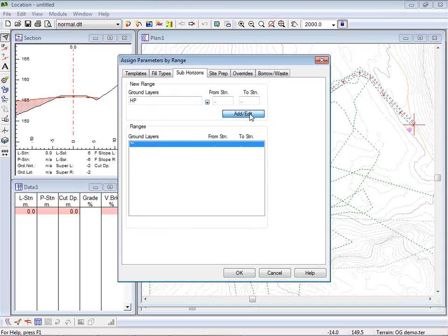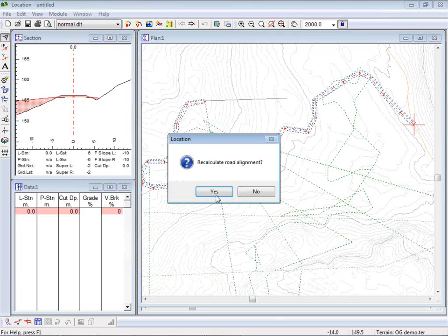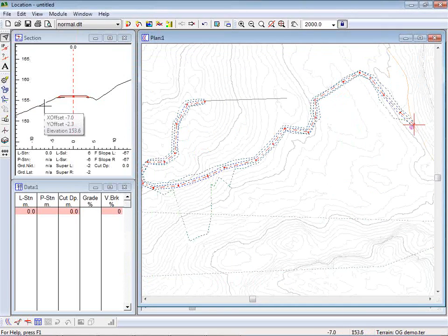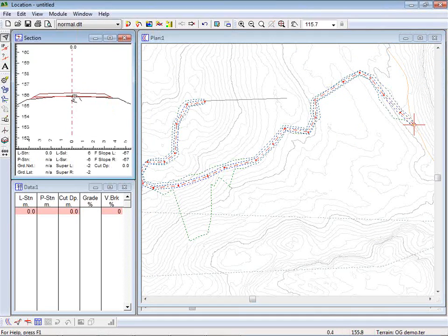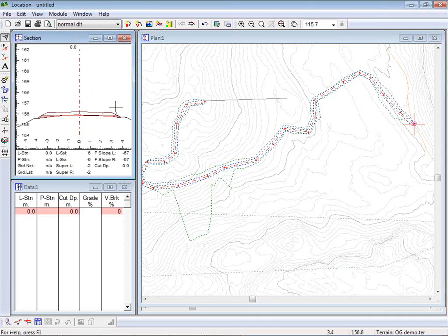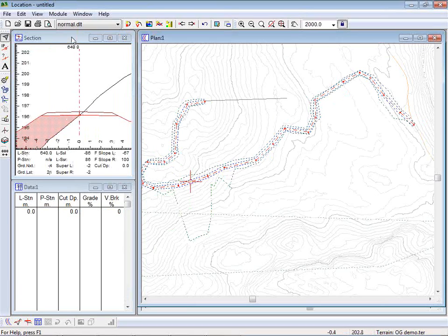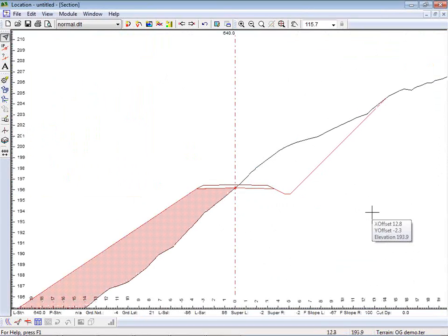Right, so I'm applying hardpan, add, edit everywhere, and immediately my cross-section will sort itself out because now I have a reasonable material in the ground. And is everything else okay about that cross-section? It looks okay. It's about 3 meters wide each side, or 6 meters total. Got some crown on it, and seems reasonable for a forest road. Immediately looking at this, I now see an issue here. Looks like that should be full bench cut. This is where we've got our steep side hill.